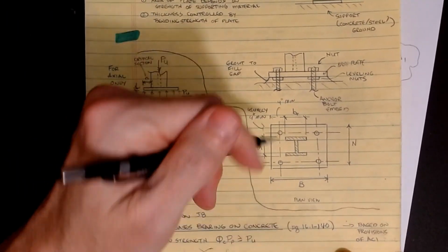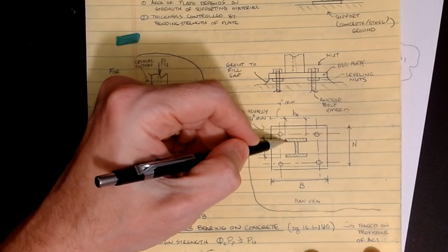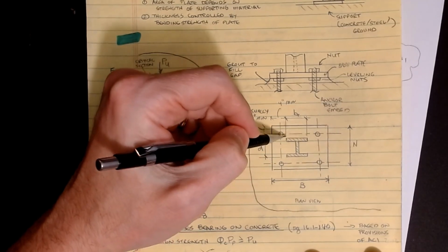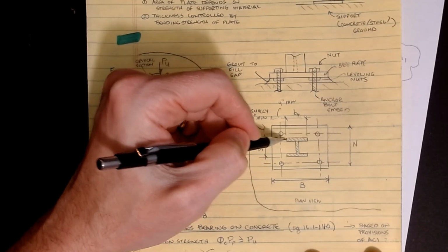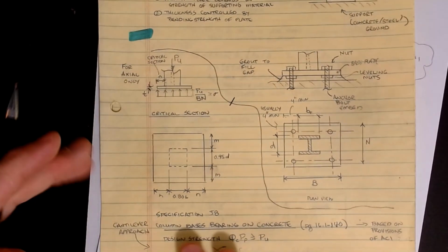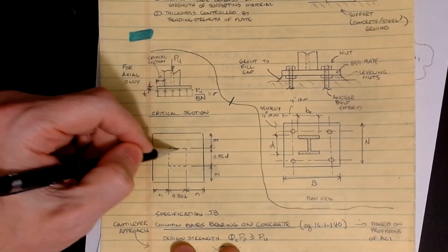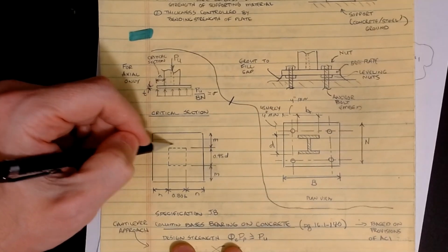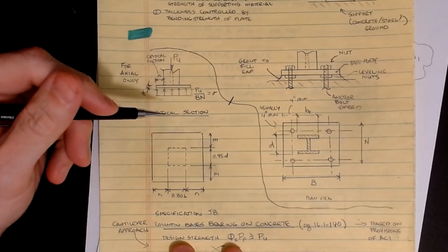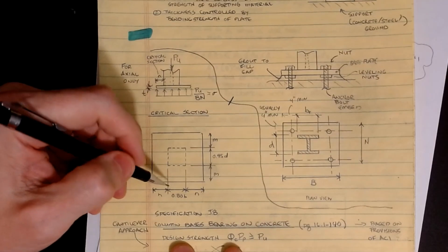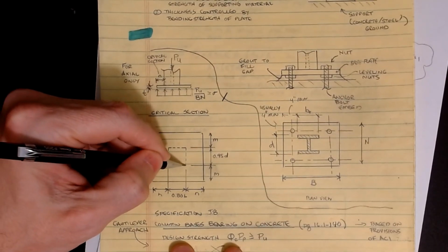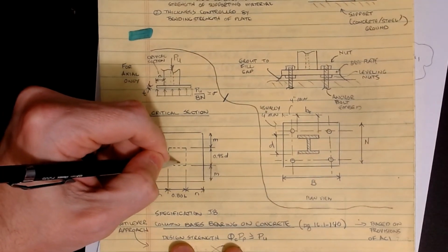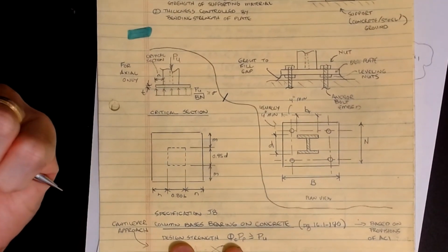Now, this failure idea that we have, I had a failure plane going through here and a failure plane just on the edge of the flange. It's not exactly at the edge. It's actually inset a little bit. If I draw those lines, there's this critical boundary that develops, and again, we're looking at kind of an I-beam happening here, and we're going to call the width of this guy. Again, we're looking at the orientation as though it were an I.